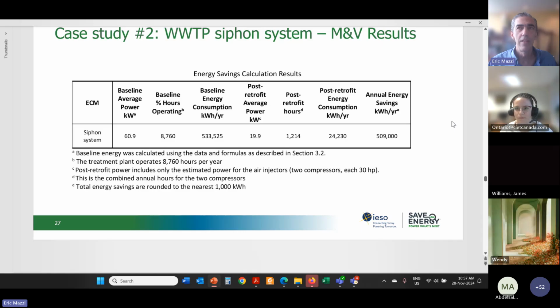The IPMVP core concepts, and I would say the same for ASHRAE 14, 2023, which is another commonly used M&V protocol, are not that prescriptive in general, especially the IPMVP. There are certain principles, like EVO and the IPMVP say, you actually have to make some measurements on your as-built system if you want to call it M&V. Otherwise, it's stipulated savings and it's really not doing M&V.